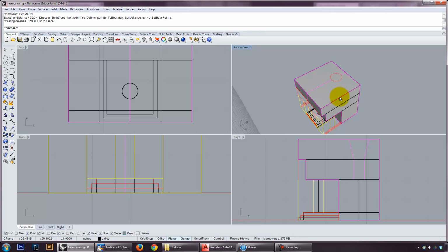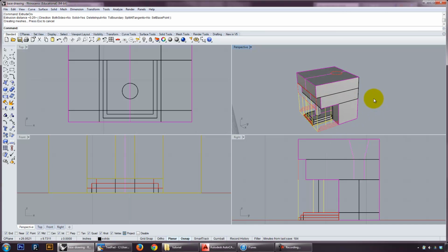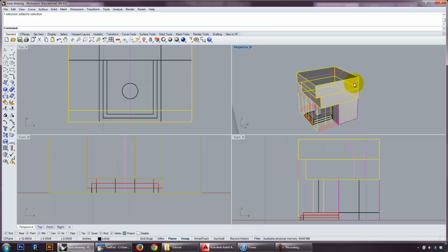The last piece of the puzzle is going to be this cavity here, this aperture. Okay, and the way that I could model this in two different ways, basically. But I'm going to go ahead and show you both ways. So the first thing I'm going to do is basically just model this as a positive and then Boolean it out of this geometry. Before I do that, I need to make these two things a solid, or it's not going to really work too well. So just join these two together, and I'm going to say Boolean union, and now they're treated as one object.